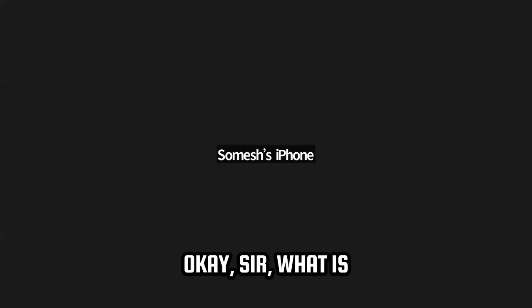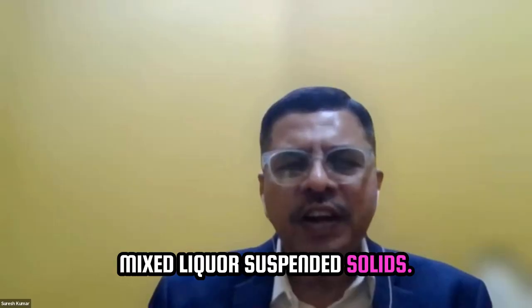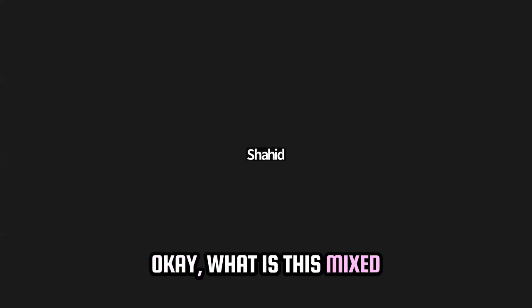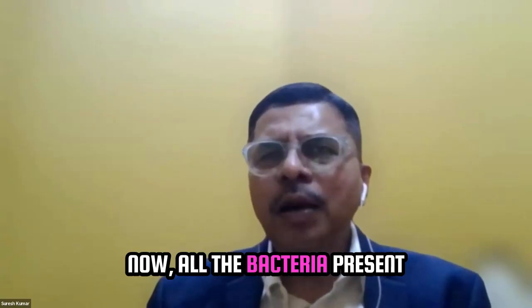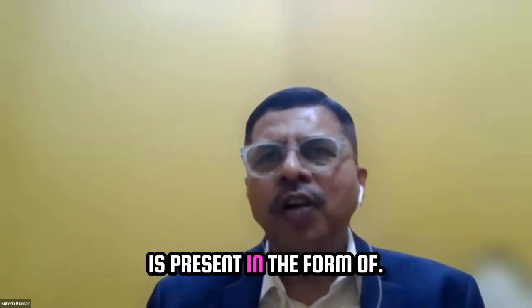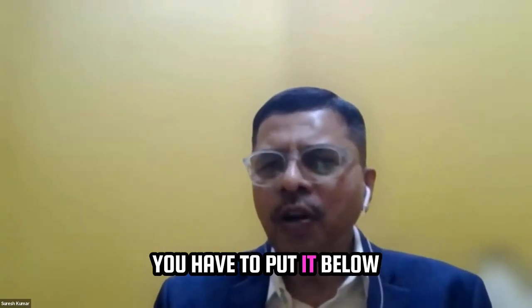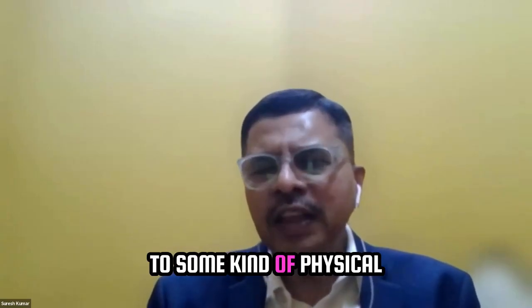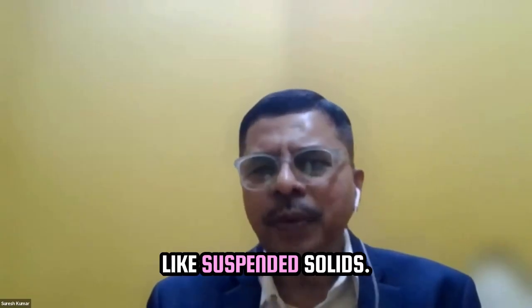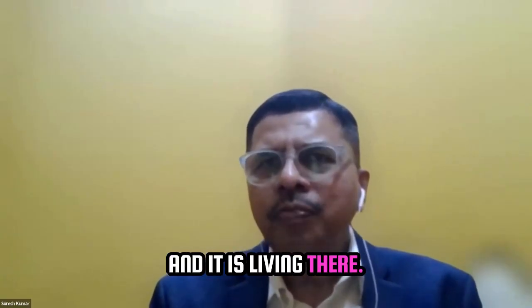Sir, what is meant by MLSS concentration? MLSS is an abbreviation for mixed liquor suspended solids. What is this mixed liquor suspended solids? Now, all the bacteria present in the aeration tank, like we discussed, is a unicellular organism. You can't see it with the naked eye. You have to put it under a microscope if you want to see it physically. So it is always sticking to some kind of physical substance, like suspended solids. So bacteria is attaching to suspended solids and living there.